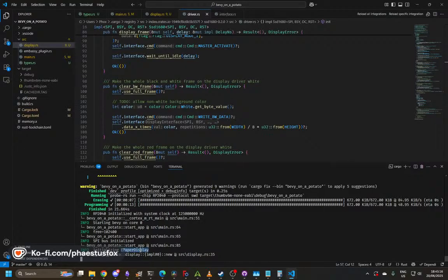So it's initializing the display, and if I poke here and here, it's busy. Okay, so maybe it's not setting the reset properly, because it said something. Well, the thing is maybe if I just wait, maybe it's just a timing thing. So reset is pull low. One thing I could do is pull the screen, just pull it low so that the chip moves on.